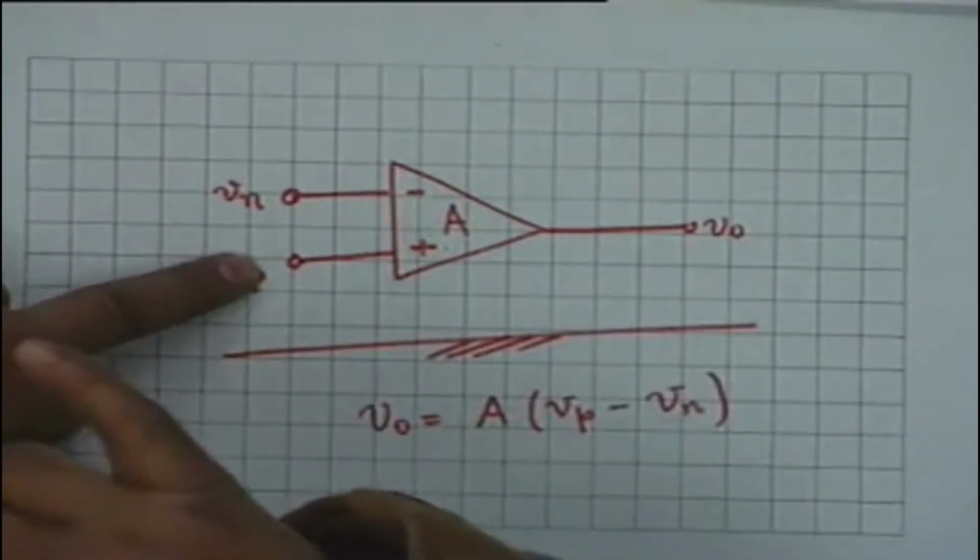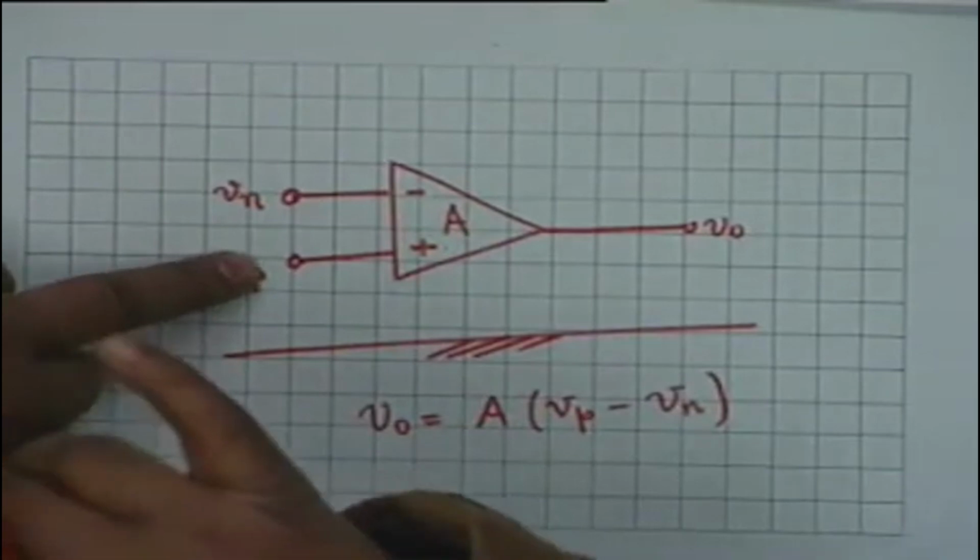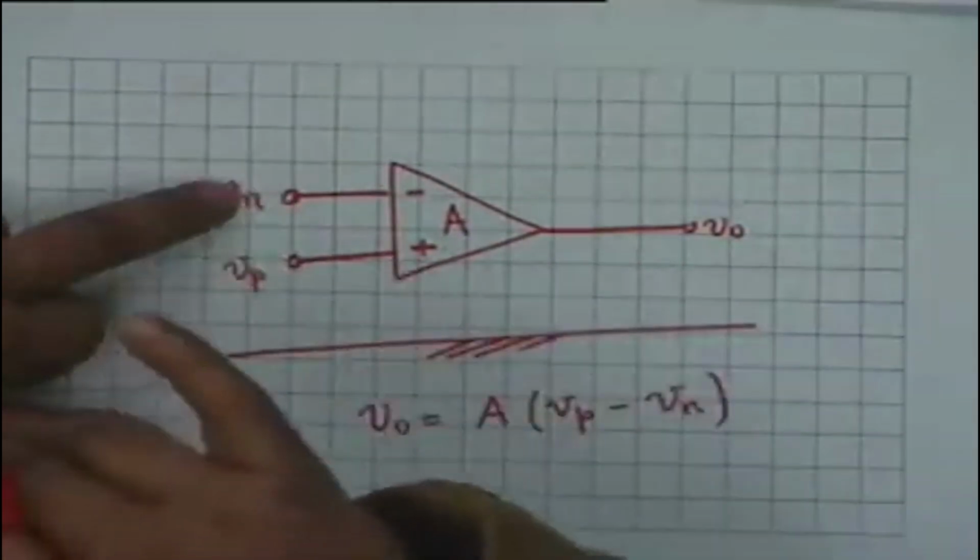On the other hand, you might require a minus 1 volt, then you apply the input to the inverting terminal. All right, so it is a more versatile amplifier chip than the conventional amplifier, where there is only one input and one output. There are two inputs here which can change the sign of the given input voltage.